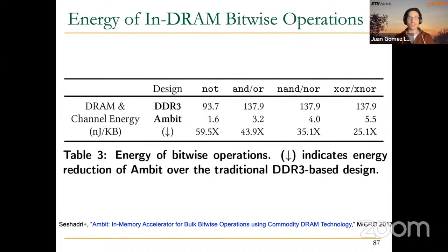Well, essentially, intra-subarray is what we explained about RowClone. In RowClone, we have the DRAM subarray. One of the proposals in the RowClone paper is called the fast operation mode, which is intra-subarray and consists of activating one row, then activating the sense amplifiers, and then activating the destination row.